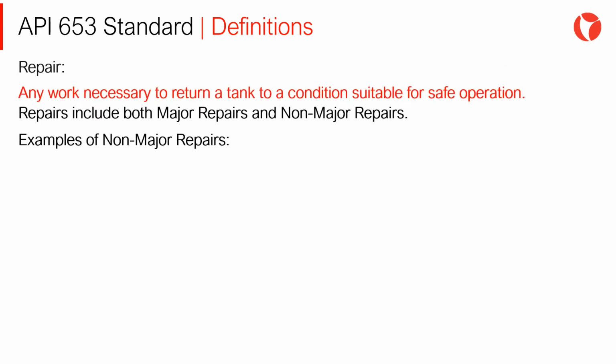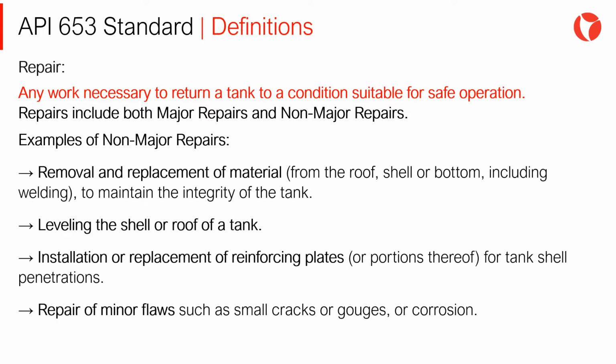Repair: any work necessary to return a tank to a condition suitable for safe operation. Repairs include both major repairs and non-major repairs. Examples of non-major repairs are the following: removal and replacement of material, leveling of the shell or roof of the tank, installation or replacement of reinforcement plates, repair of minor flaws.